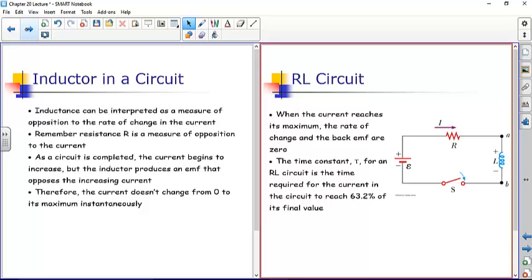So what we have is this RL circuit instead of an RC circuit. In an RC circuit, the current goes to a maximum initially. In an RL circuit, the equilibrium condition is not the capacitor being fully charged. We reach a current and the inductor reaches a steady state situation, and therefore there's no change in current and the inductor just acts as a wire. The only time the inductor works as something other than a wire is when you're changing from one current level to another.